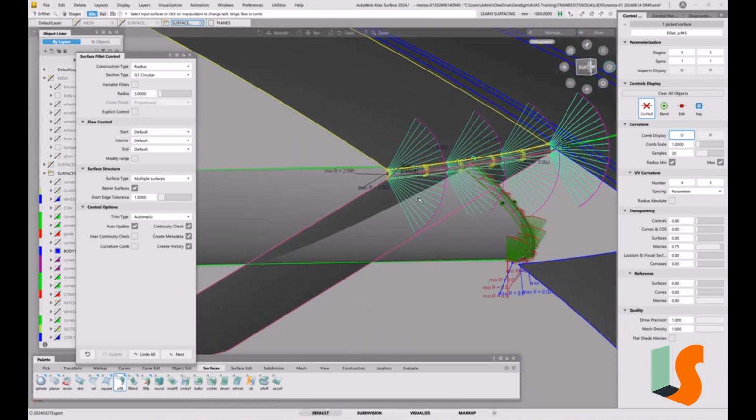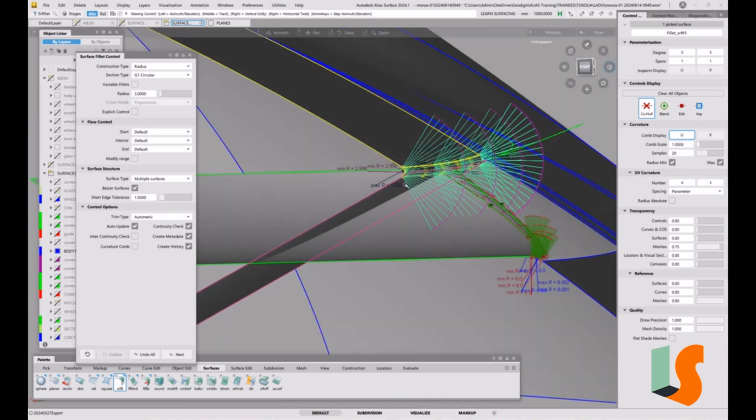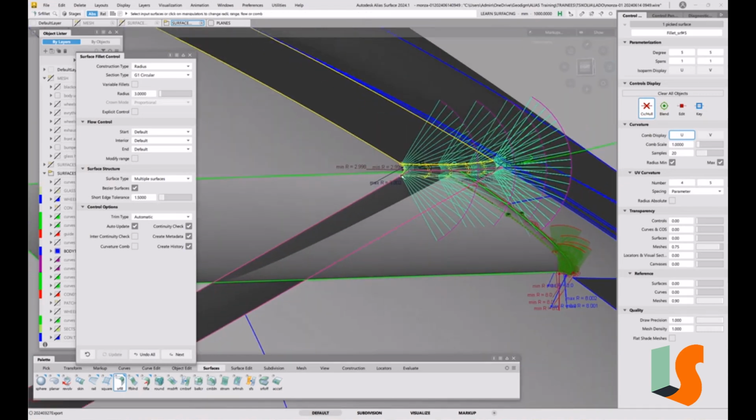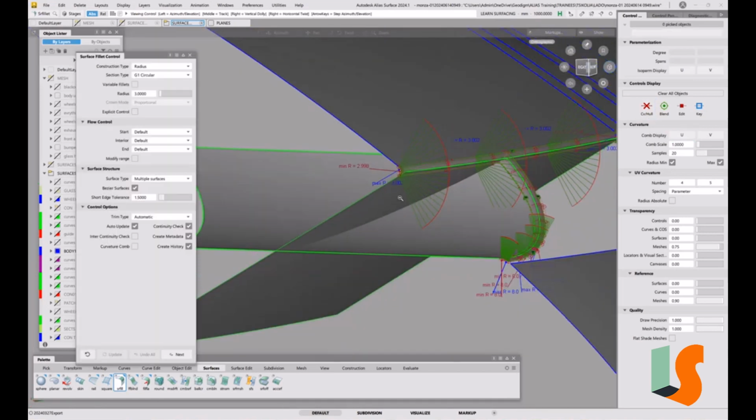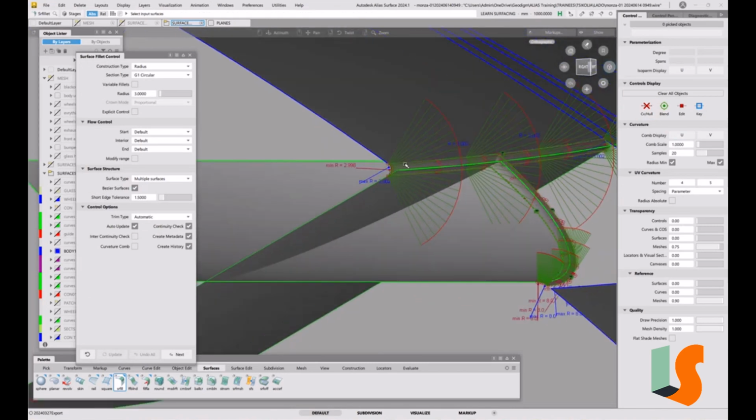And in these areas, this is quite common, you have something like this, and what you could do from an engineering point of view to create that intake is we could actually have another draft surface coming back from a point down here where it's less visible, and you just put in a draft surface down here, so we actually have an intake, because I'm obviously closing off the air here, which is not the thing to do.